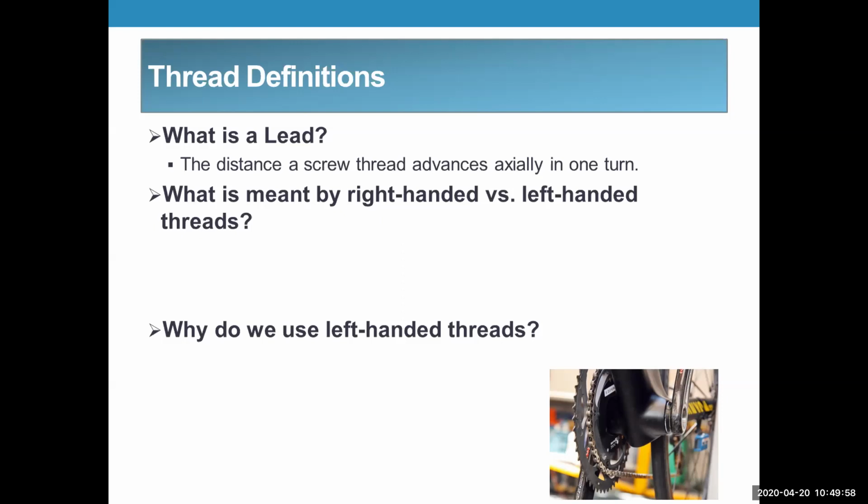So would lead be the same as the pitch? Probably. Yeah, I think it is. Because when you turn a 1/4 bolt 1 turn, you turn it 1/20 of an inch. Right, exactly.